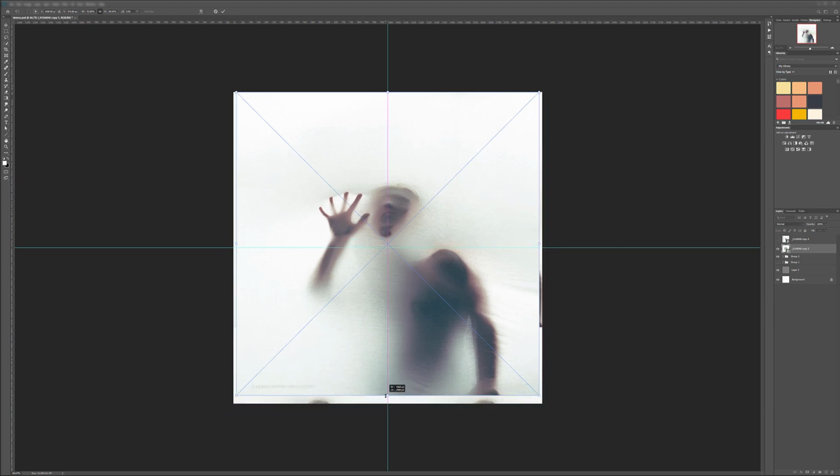It does not stretch proportionally; it will stretch to fill all of it. This is something you need to understand: if you have an image and you maybe want to place it on the side of a box, and you use parametric for the object, it will scale with the object, which is kind of nice, but it will give you distortion, so you need to be careful when you do this.